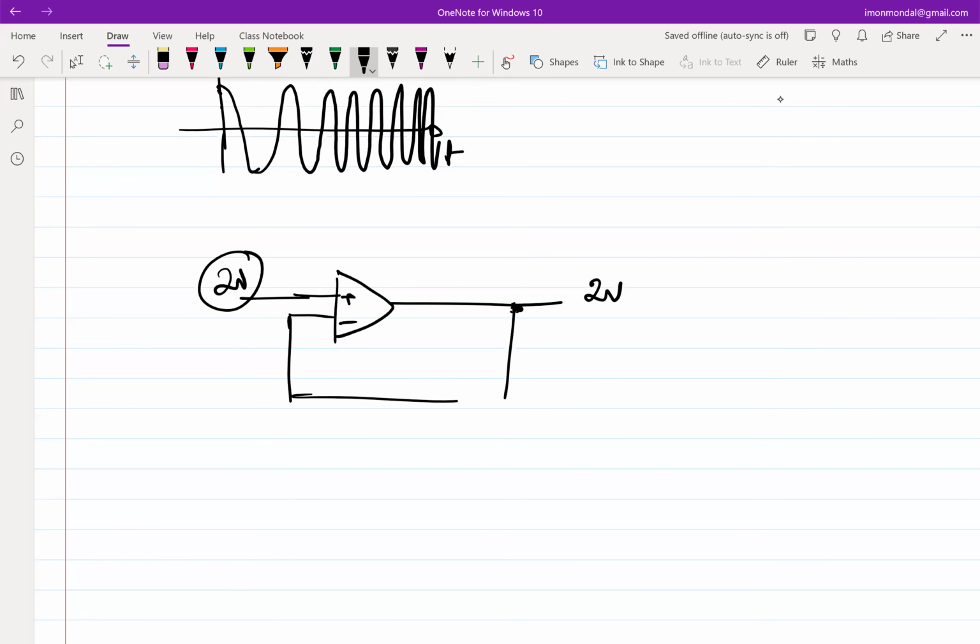So which means that if I have something off chip which is extremely reliable, I'm going to use it to generate my on-chip references. Now, you might ask, if I have something reliable, why don't I use it directly? Why do I need to bother with something here? The answer is the same as in this case: when you have this 2 volt off chip, why do you need a buffer on chip?